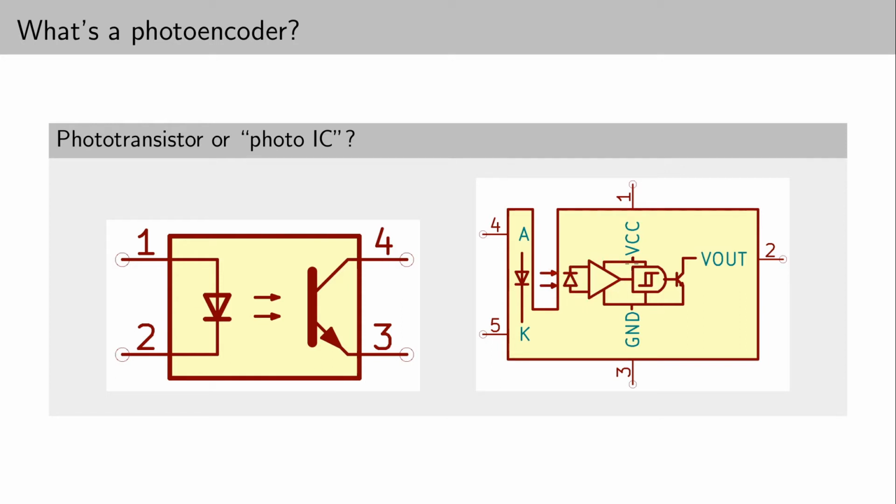And then you have some kind of comparator or other device with hysteresis. Here it's drawn as a Schmitt trigger gate with this little hysteresis thing in here. And this gives you clean switching between on and off. And here this one is shown as driving an open collector output transistor stage.